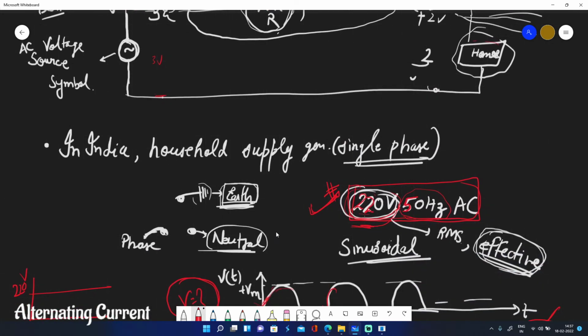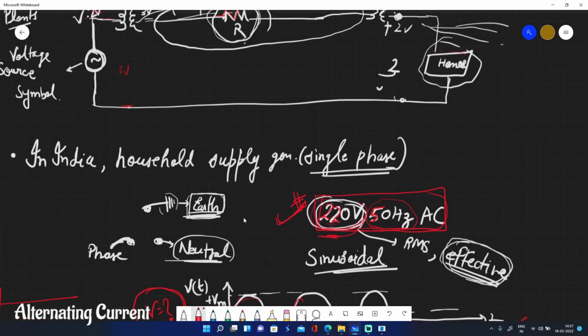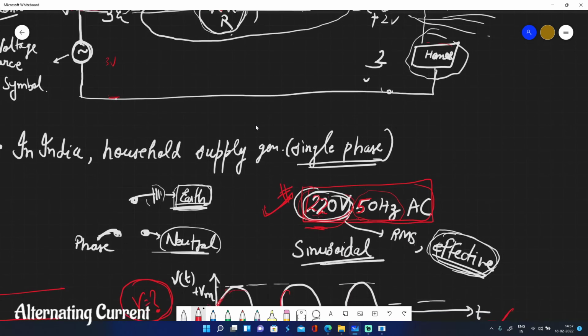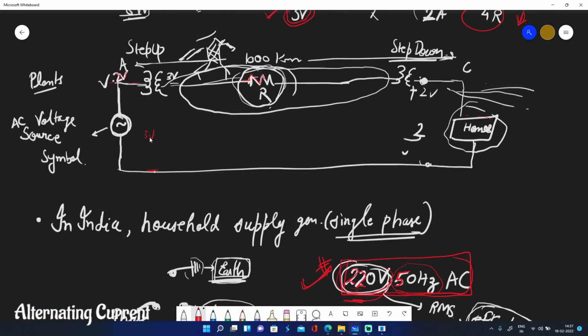Now, I was giving some example here, 3 volt, and if it is AC, the same thing applies. How am I denoting this number? This is RMS. Every value is RMS. If anyone asks how we are using these constant values in AC, whether referred to or not, by understanding you must know that these are RMS values.